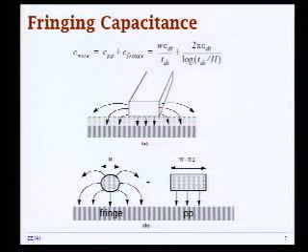And then you basically just made the wires thinner and thinner as we scale technologies. And then in that case, we no longer have this really parallel plate thick wire assumption. It's more like this really converges to this case where you have more of a round piece of metal going on top of dielectric, and then we have to start worrying about this fringing capacitance. So parallel plate was dominant long time ago, and then with technology scaling, this fringing capacitance became really the dominant